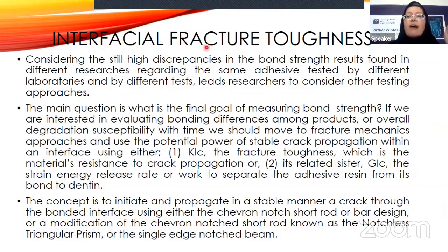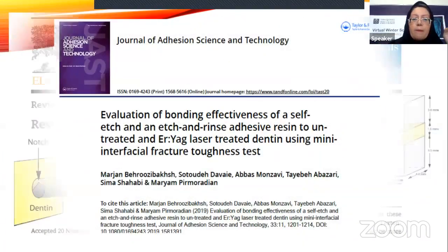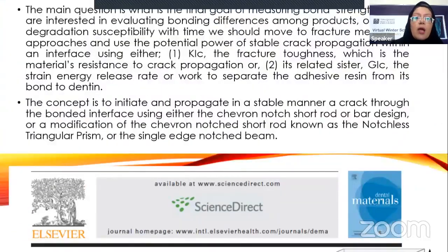In interfacial fracture toughness, we usually prepare a pre-notch here, and apply the load via different test methods, maybe via 3-point bending or 4-point bending flexural strength.